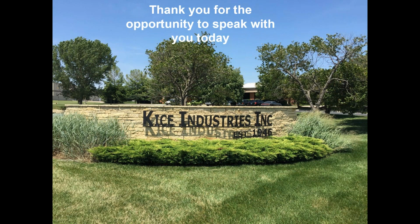Pluses, you can get a lot more filtration out of the same size filter body as you could with a filter bag. But again, remember that if we use filter cartridges, those need to be applied at a much lower air to cloth than we discussed today. These were based on fabric filter bag numbers. Lower air to cloth, I would say as a general rule of thumb, below a 4-to-1 air to cloth is where you want to be on a filter cartridge, and most times below a 3-to-1, a 2.5-to-1 is where you're going to want to be with cartridges. So again, a good time and a good place for both. Just be careful that you're aware of what you're working with, and if you are changing from one to the other, what effect that's going to have on the entire air system.